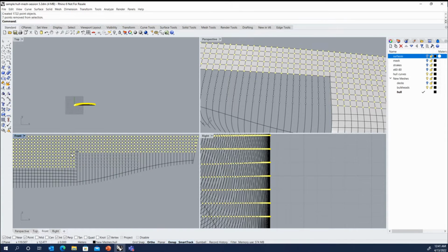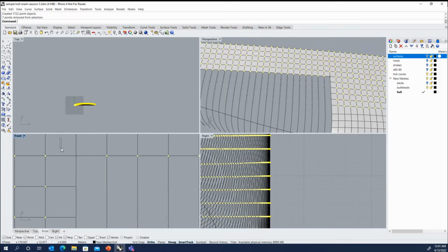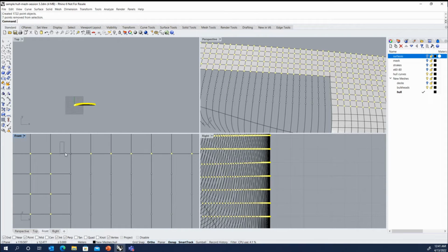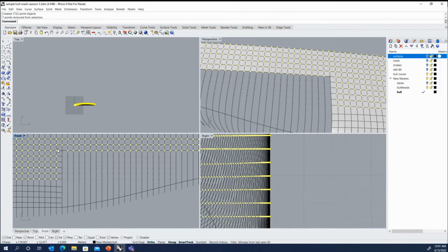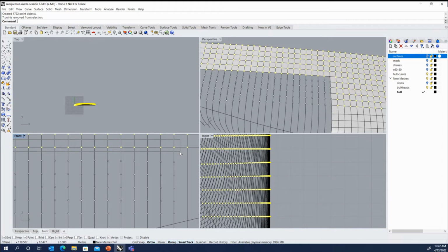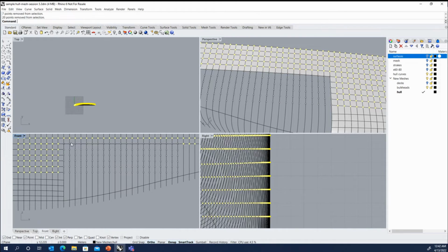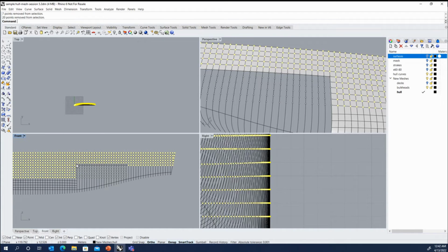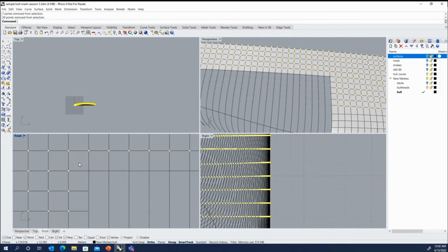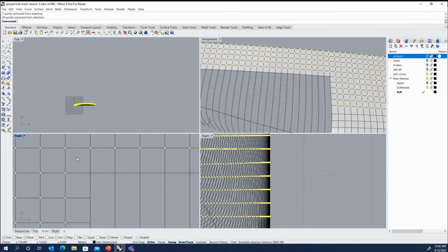This is another little trick. If you have difficulty selecting, you can zoom in, and I'm holding the control key down and I'm holding the left mouse key to start my selection, but I can zoom in and out with the wheel. So I can zoom out and then zoom back in at the other end if I need a little more control over where to start and stop the selection. Because when you're zoomed out, sometimes it can be very difficult to, if you go to pick a spot, it's going to grab the wrong object. If I'm trying to drag a window rather than select an object, I need to zoom in close enough that I have some blank space that it won't automatically select the nearest point or curve or mesh.